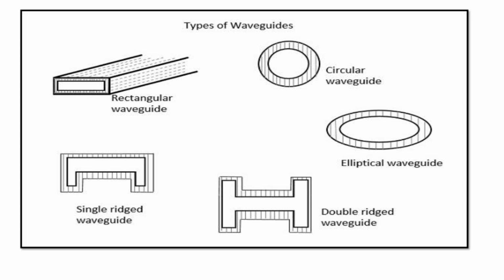Parallel plate waveguides are always finite in width with fringing fields at the edges. Electromagnetic energy will leak through the sides of the guide and create untraceable stray couplings to other circuit systems. Thus, practical waveguides are usually uniform structures of a cross section of the enclosed variety. The simplest of such cross sections, in terms of ease both in analysis and in manufacture, are rectangular and circular waveguides. Today we will discuss rectangular waveguides.